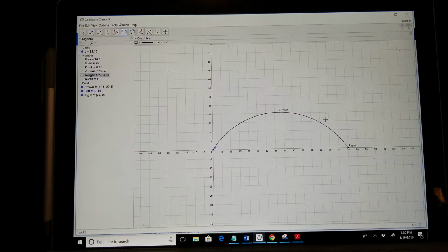Now on my force diagram, I don't want to draw a whole bunch of little segments because I have to discretize this into a series of point loads. It's a uniform load. I'm going to choose 8 because it's really easy to get 8, and I'll show you how to get 8 right away.